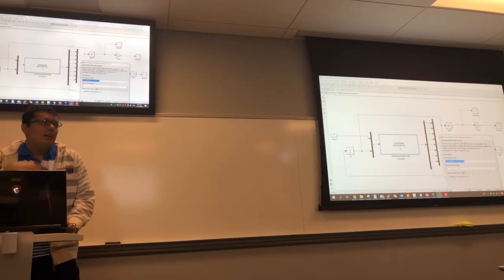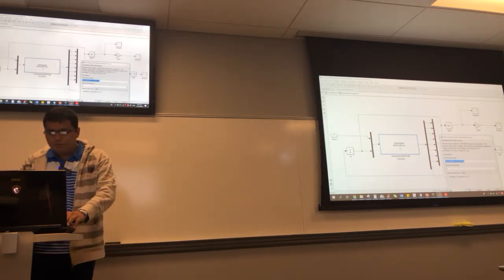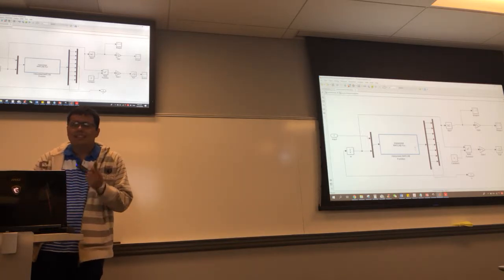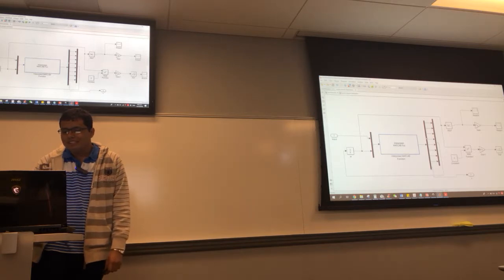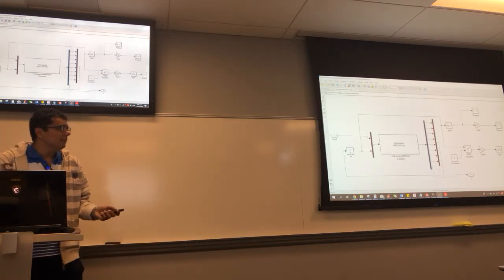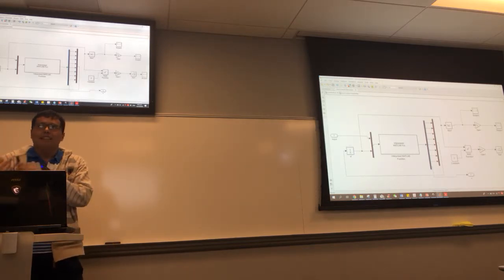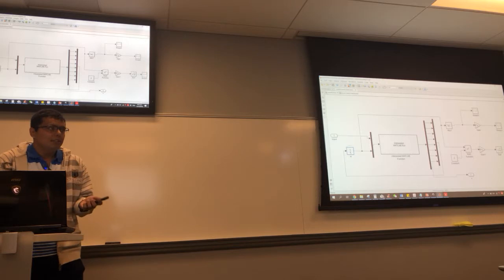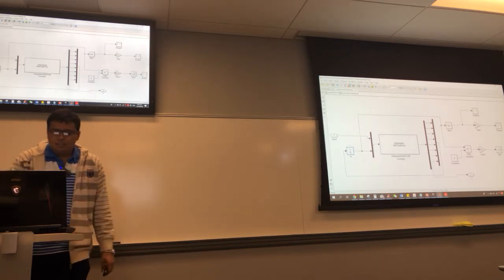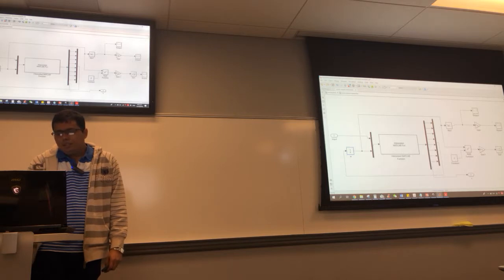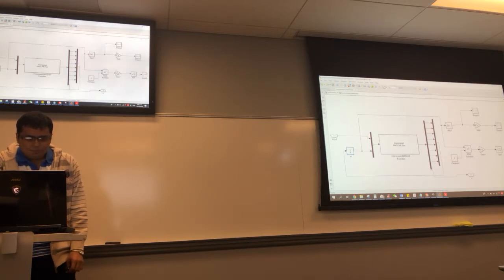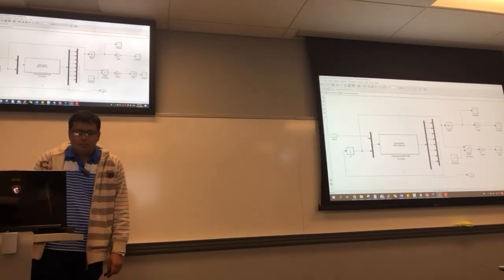I implement the algorithm, the calculations, in a MATLAB function, but this is something tricky for Simulink. The output of these kinds of blocks, you need to split with a MUX in order to update and integrate, because the update laws are given in terms of the derivative, so you need to make a numerical integration to obtain the updated W, the updated V, or the weights. And here is the calculation of the norms. Basically, this is the norm to calculate. And the algorithm was built all by myself.